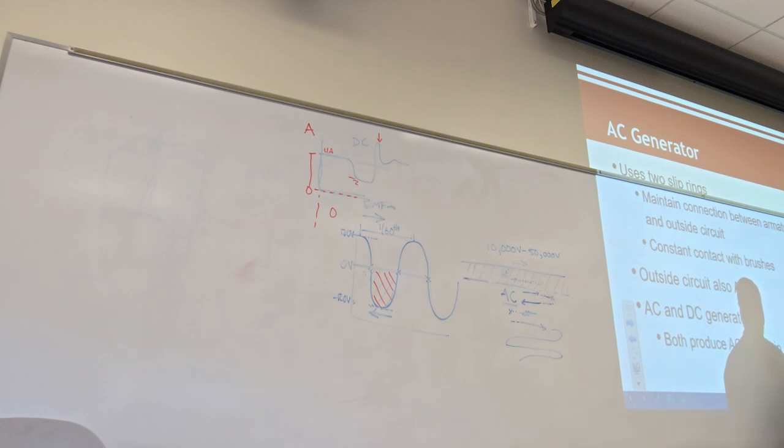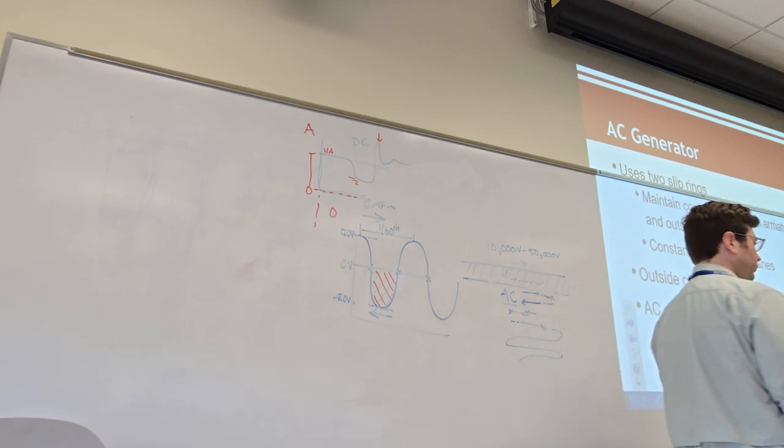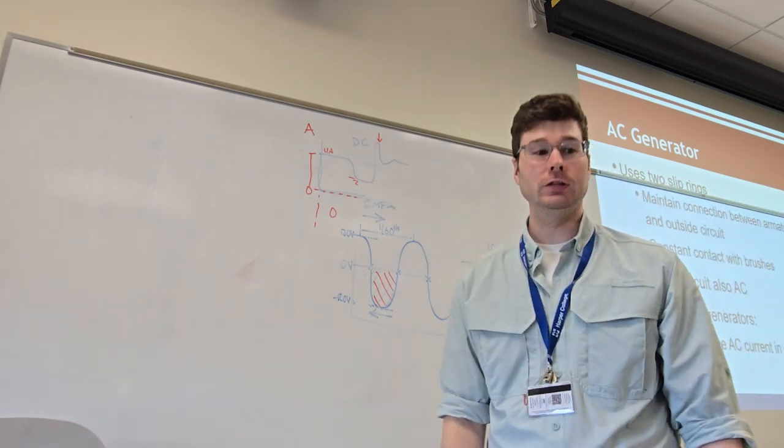At the right times of the cycle, it will be touching this cylinder as it's traveling along, and then when the missing part comes up, it won't conduct current, obviously. It'll be in the right part of the cycle to mechanically switch over the direction of the current using these brushes.